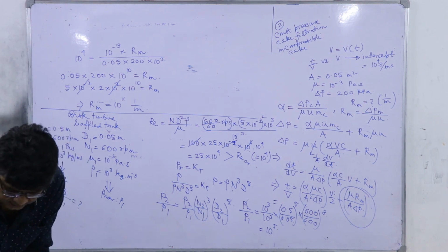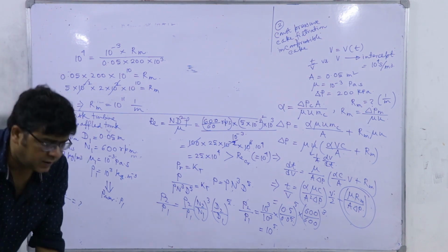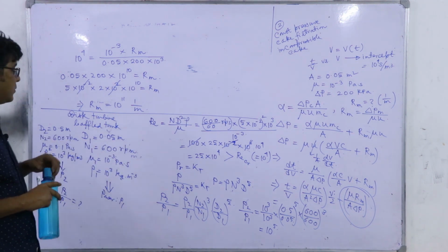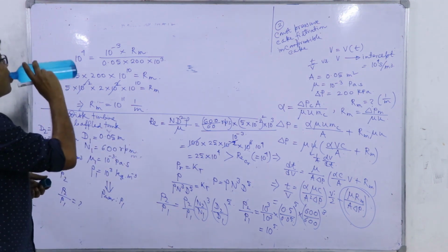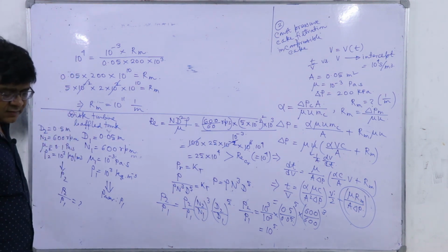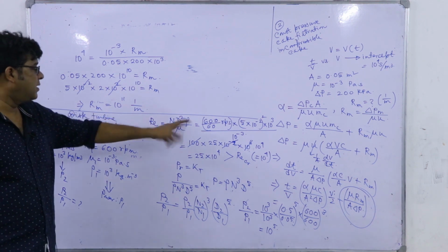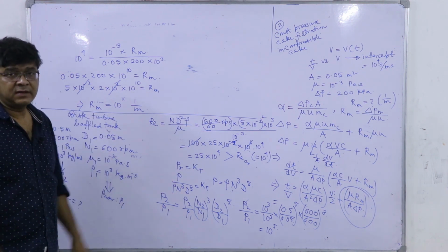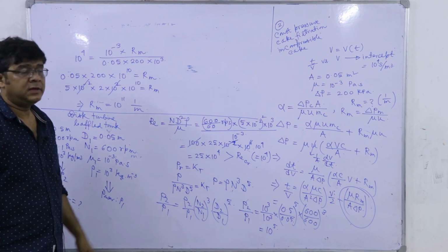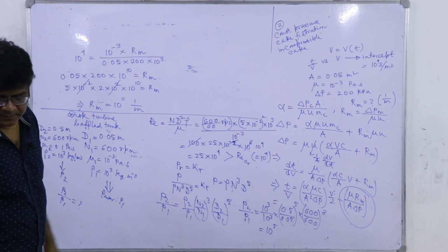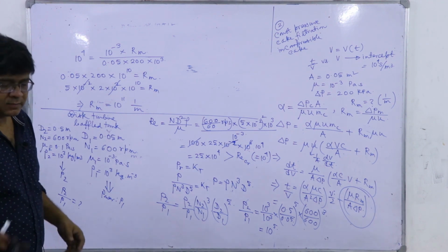Typically there is no effect of this viscosity change because it is operating in the turbulent regime. But if we find this Reynolds number is less than 1, then definitely the viscosity will be affecting, and the power number will be equal to some constant divided by the Reynolds number.